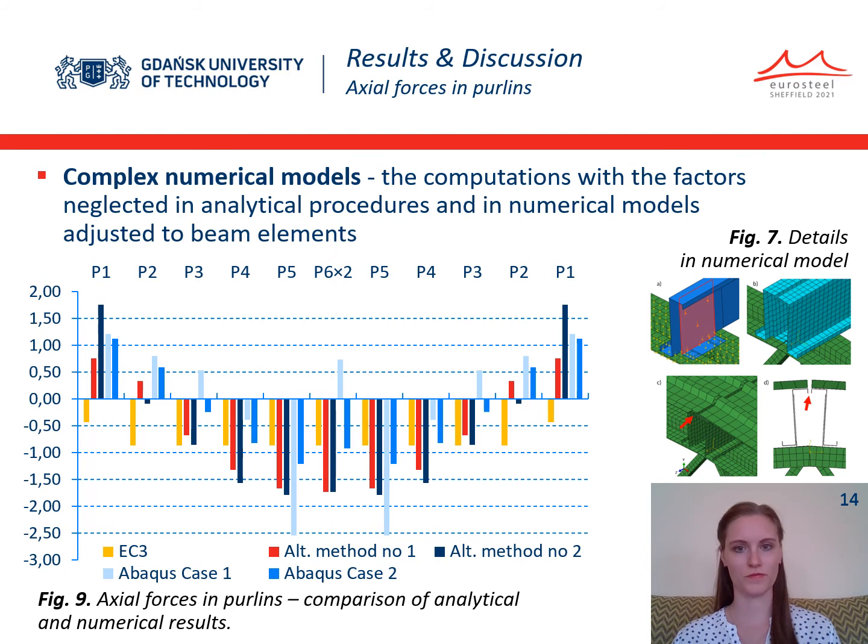Another factor which may produce discrepancies was that numerical results were achieved for the case of a pitched roof, and that is why the axial force in ridge purlins is lower than in the neighboring ones, and it may even change the sign.